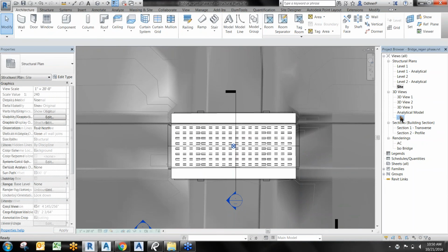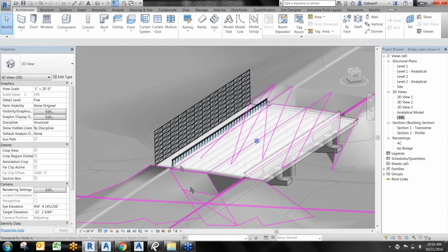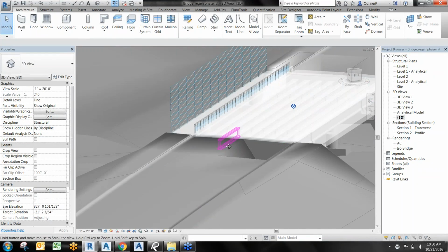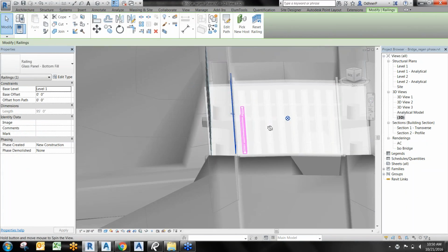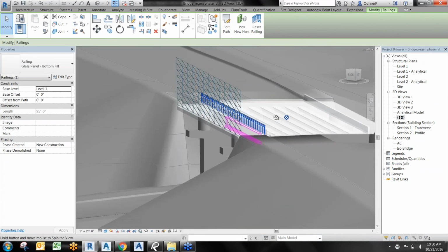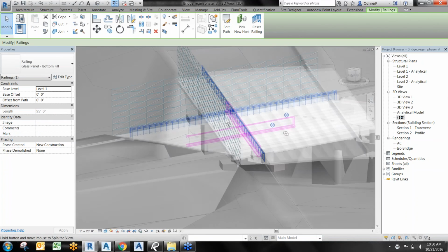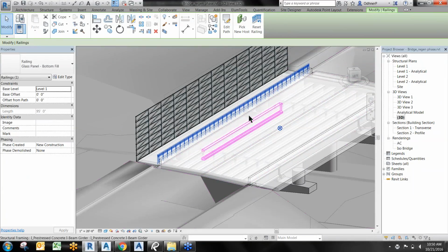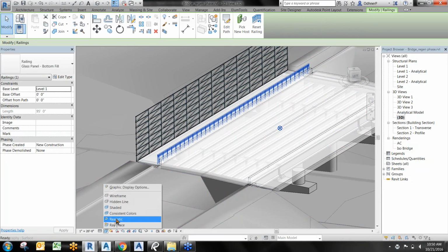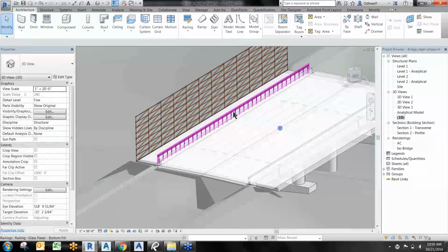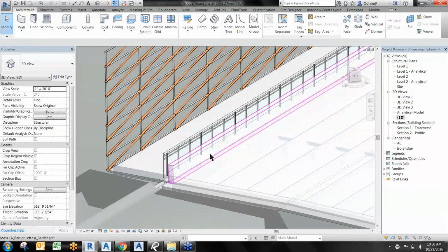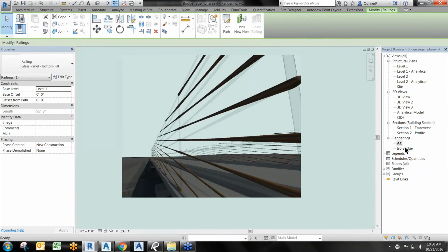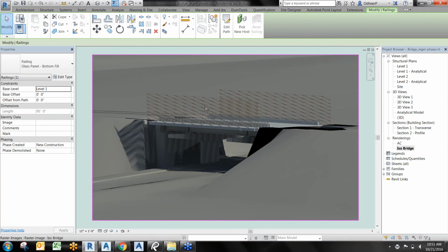So when I check that and go to a 3D view, you're starting to get some pretty nice features here. I'm going to grab the railing and do kind of a quick rotation here. And so really you're keeping the fidelity of Civil 3D surfaces, and you're also coinciding with the Civil 3D alignments, and you're also able to go in here and add some pretty nice Revit features, above ground features here. And from this point we can start doing our renderings and save these renderings, and basically this is the final output of today's demonstration.